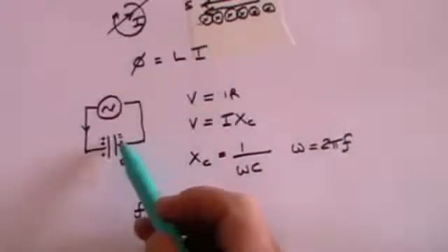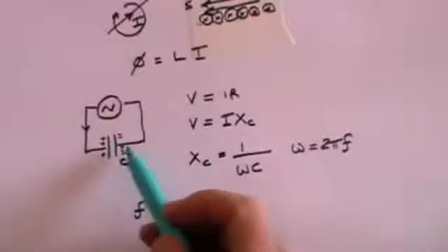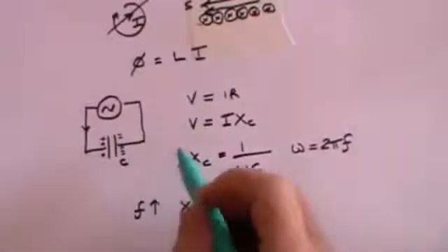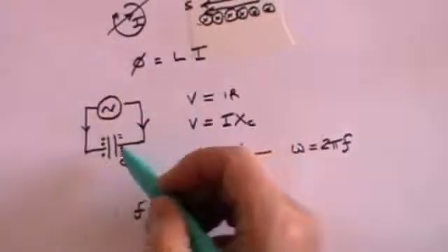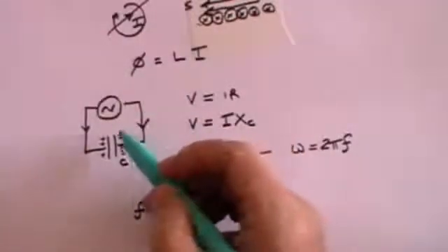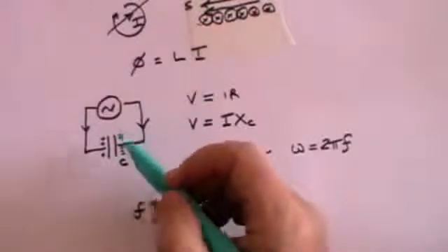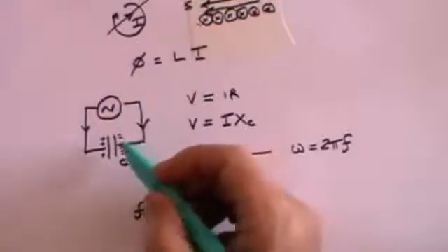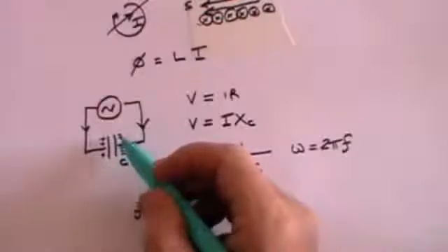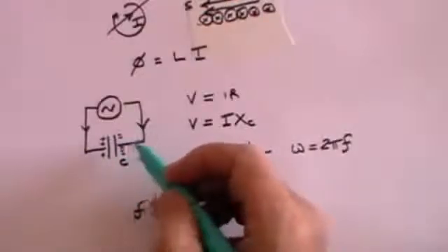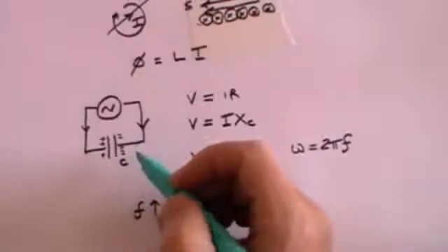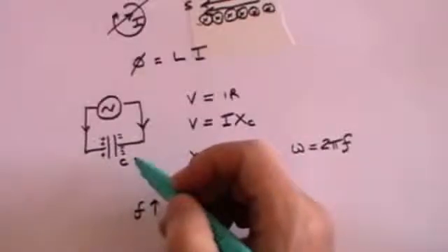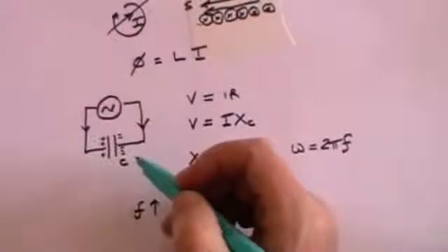Not only do they repel the electrons from this plate, but they also impede any further electrons that are coming in this direction wanting to join them on the plate. As the charge builds up, then like charges repel. Consequently, the charges that are already on this plate will repel the charges that are trying to come and join them on the plate, and ultimately they will stop the charges from flowing altogether.